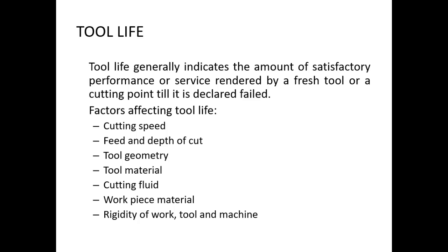And next one, cutting fluid. During cutting operations, I must take a cutting fluid which helps to reduce the temperature at the cutting zone, reduces the friction that exists between the two metal pieces, and carries away the chips coming out of the process. Then workpiece material obviously, and rigidity of the work and tool machine, etc. So these are a few factors that affect the tool life.